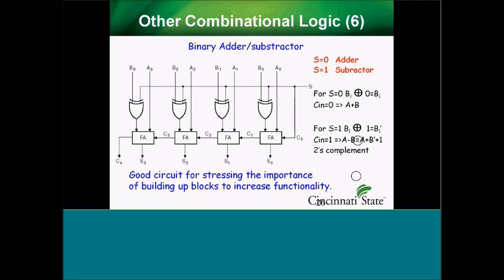Okay. A couple of interesting other things for adders that comes up is that if you take this with a little bit of external logic, you can turn it into an adder and a subtractor. I used to run a lab at OU where we built these. I don't have this one at Cincinnati State, but it certainly can be done. And it's a really cool circuit. One of the things you'll see is that you have a selector line S, and so if S is a 0, it does adding. And if S is a 1, it does subtracting,